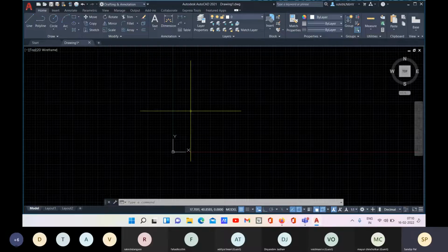in the previous class I have mentioned about UCS and WCS, how these systems work, and AutoCAD only understands the default values in terms of UCS, right? So you all remember that if you type normal x comma y comma z values or x comma y values, it will count as UCS values. As per your UCS alignment, you will get the result.